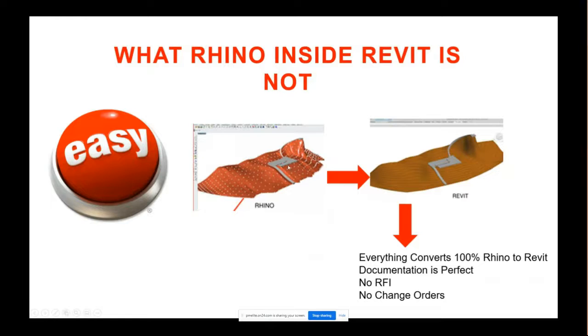But what type of element would this be inside of Revit? What size would it be? What type that you pick within, what type of family would it be, right? Is it going to be a system family? Are you going to bring it in as unintelligent geometry just for visualization, right? Rhino doesn't know that, so you need to tell it that. That's why you need interaction. You need to be able to mold your workflows so that it's specific to your project, your model.